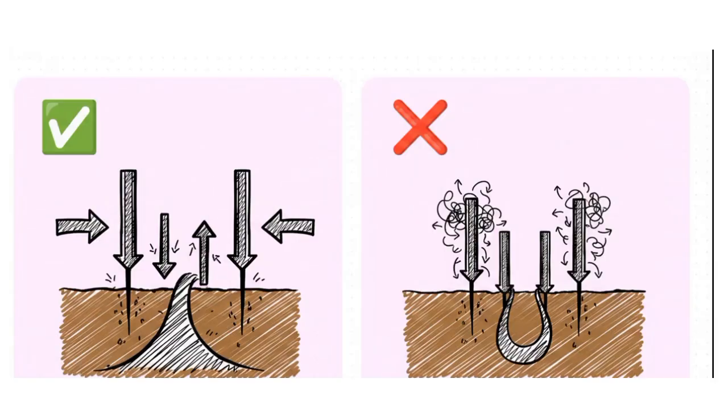Now you might hear about another setup called the Wenner Array, but for groundwater exploration, the Schlumberger Array is generally vastly superior. Why is that? Well, first off, it's significantly faster, because the field crew usually only has to move the two outer electrodes, leaving the inner ones mostly stationary.